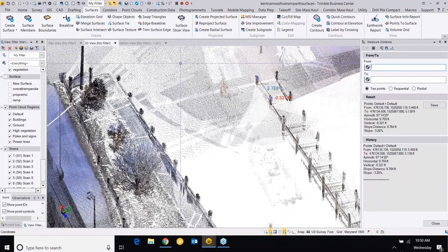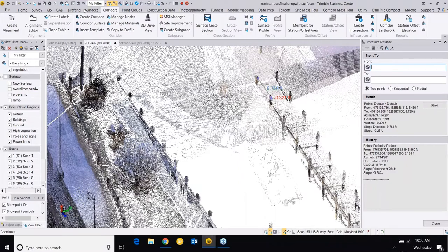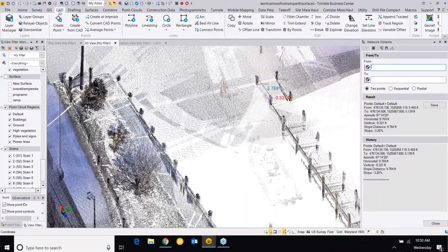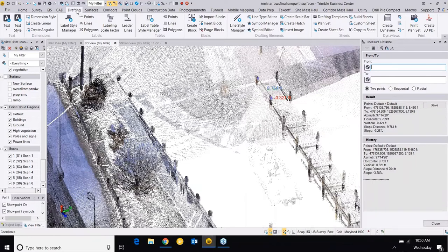You say earthwork, so if you wanted to get an earthwork report, you can get that out here. You can get a cut and fill map out of here. You can also do your quick contours on the surface. You can add your break lines. I mean, there's endless amounts in here. In the CAD here, you can make your polylines, your strings in here. In your drafting, that's where you're going to find most of the old COGO tools like that too. Yeah.